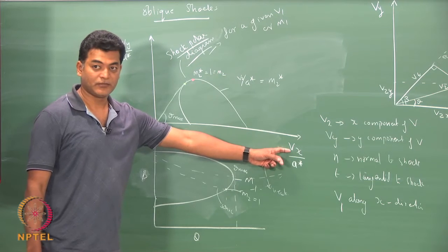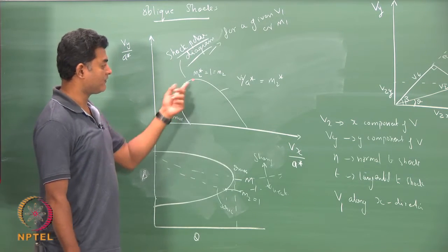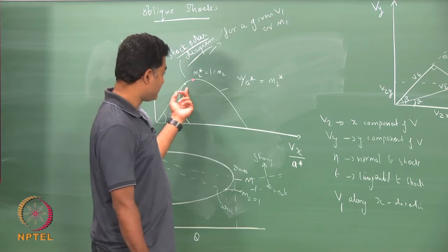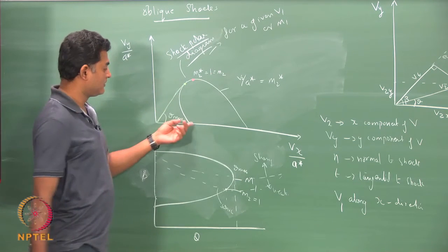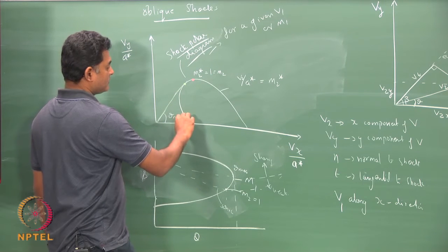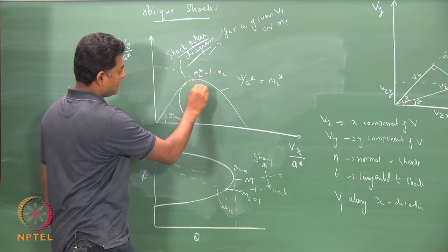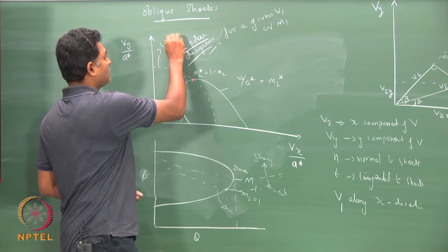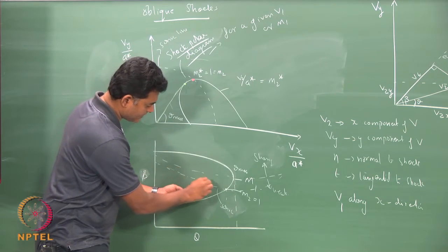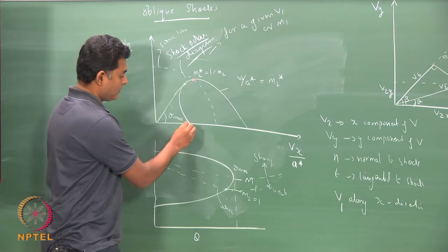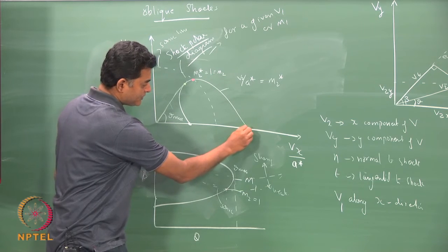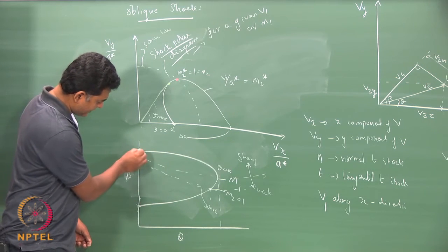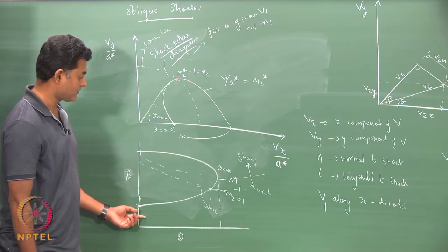So, if I know the Mach number based on my velocity components x and y, I can draw this and find the solutions where I get theta max and M2 the sonic condition. So, this is for a given M, and for other M's you would get plots similar to this, and you can find the locus of all these points which gives M2 equals 1. So, that is your sonic line corresponding to what you have seen here in the theta beta M relation, okay. And these 2 points on the x axis give me theta equals 0, which is precisely these 2 points for some value of your M1, okay.